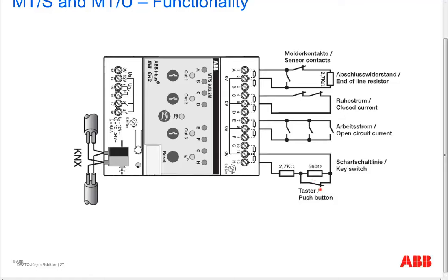And this normally closed contact would be our setting device. Here we can distinguish between three states. The system is set or unset, or any malfunction of this zone can be detected. So three states, and thanks to the resistors, this will be easily possible. Good, so that's a bit more comprehensive introduction.